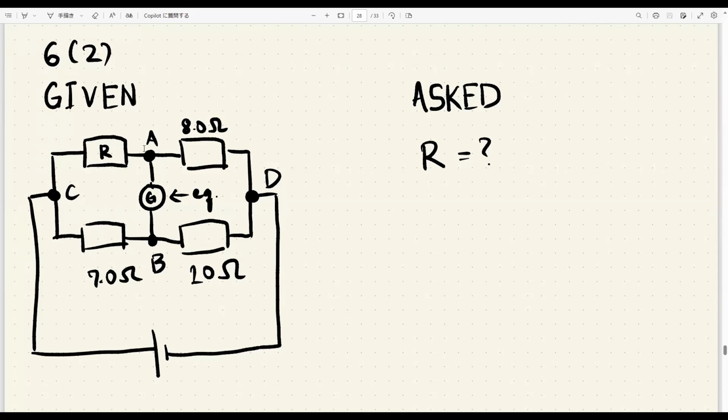That's when you have exactly the same proportion, because the voltage drop is proportional to the resistance, right? And so the resistances should have the same proportion for the voltage drops to be the same.